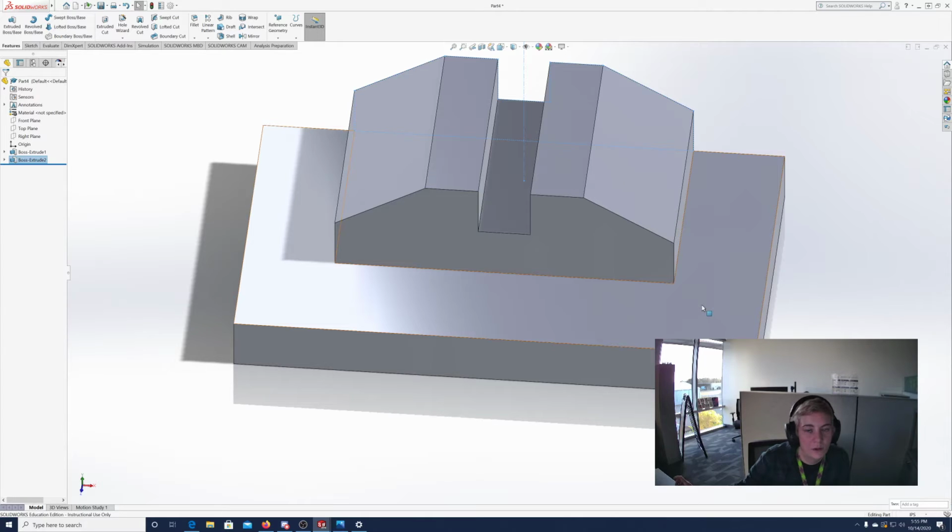But if you pick a hole size, like say 1/4 inch, and your drawing is in meters and it's like 30 meters on a side, that hole is going to be absolutely minuscule and you won't be able to see it until you zoom way in. So you're going to think, oh, it didn't make my hole, but it did, it's just that your scaling is off. So that's why it's important when you start your sketch to make sure that your dimensions and units are what you want them to be, and that everything's going to add up correctly.